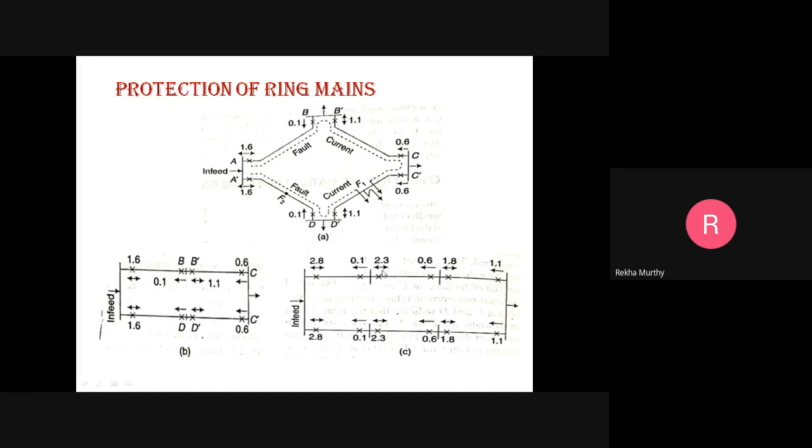So each sectionalized part is getting separated by one directional relay and one non-directional relay. If a fault current is going to occur, the relay that is going to trip indicates that it has to reverse that current. There will be a reversal of power, right? What we had discussed in the previous session. So for making that reversal of power, we require the directional relay. That itself indicates when the reverse flow of current occurs, that particular relay has to trip.